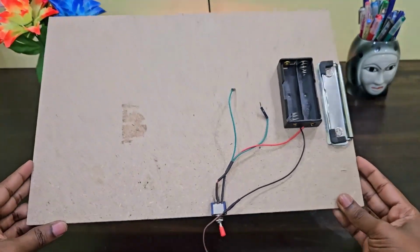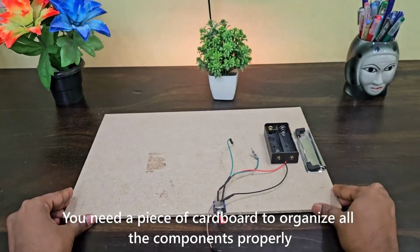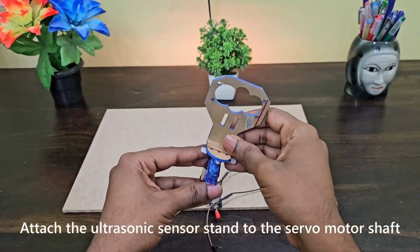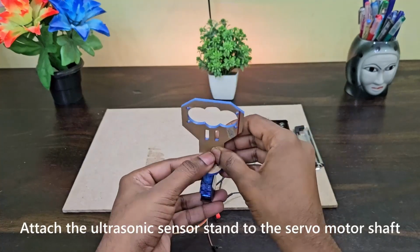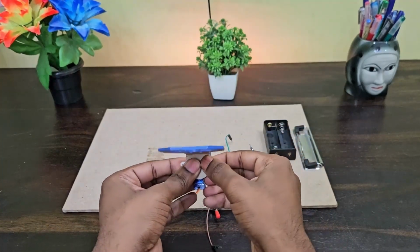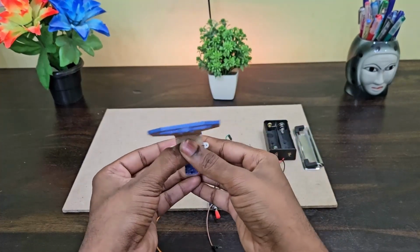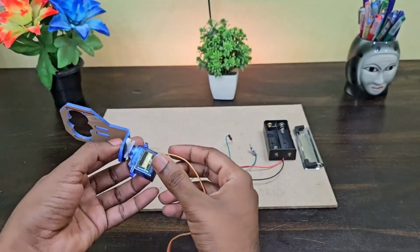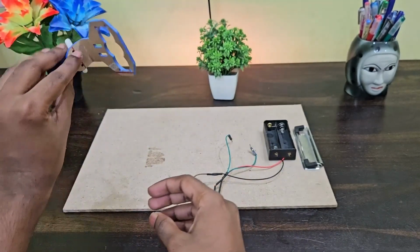In this video, we are using a plain cardboard base to mount all the components properly. Secure the ultrasonic sensor stand onto the servo motor shaft, ensuring it is firmly mounted. This setup allows the servo to rotate the sensor smoothly, enabling the radar system to scan the surroundings effectively. Make sure the stand is properly aligned and balanced to avoid any instability during movement.